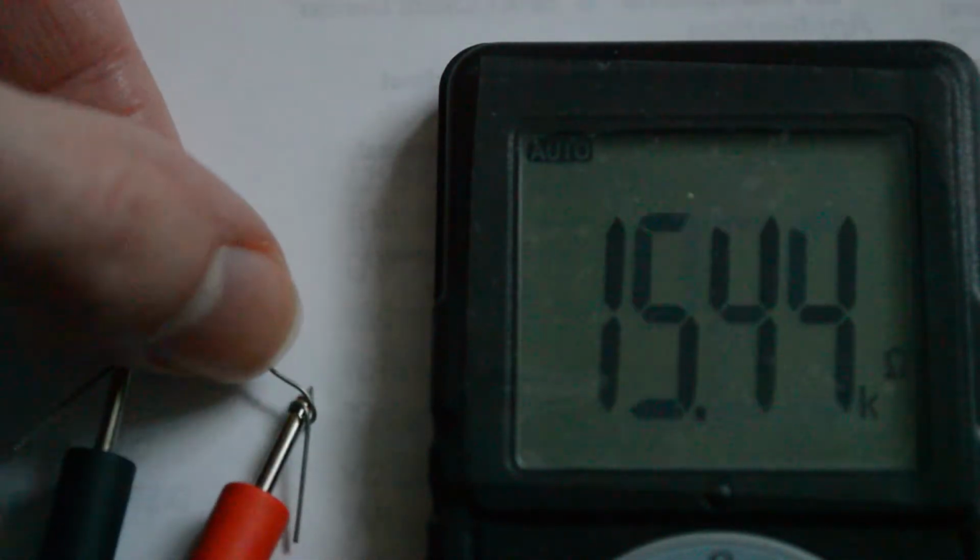Now if I shine a torch on it, off camera so my exposure doesn't close down completely, we can just about see it measures about 70 ohms. These are the basic characteristics of an LDR. It is a light dependent resistor, so it changes its resistance with light. In low to no light, it will have a high resistance, and in bright light, it will have an incredibly small resistance. This property can be very useful in sensor circuits.